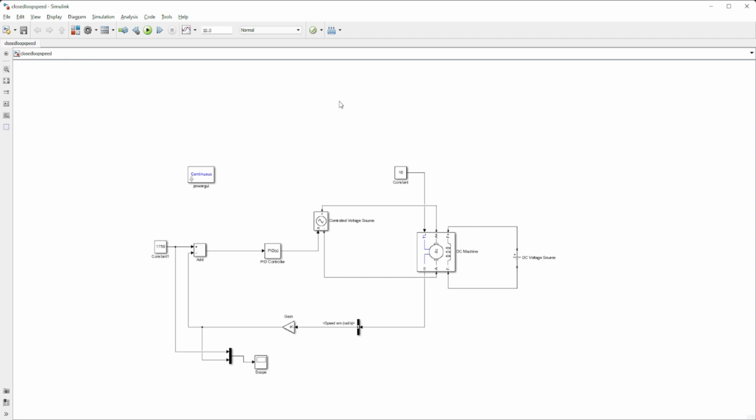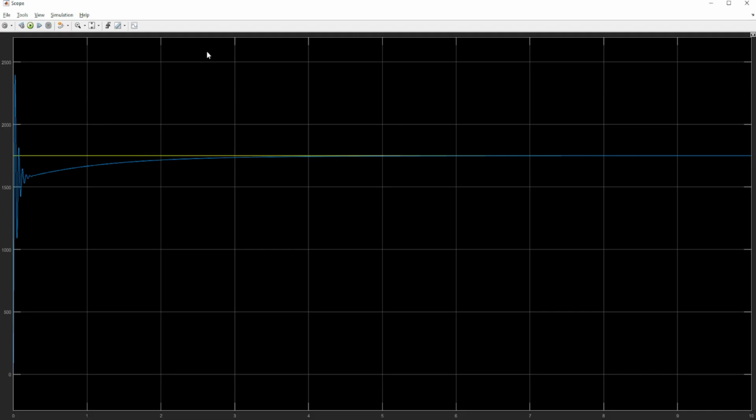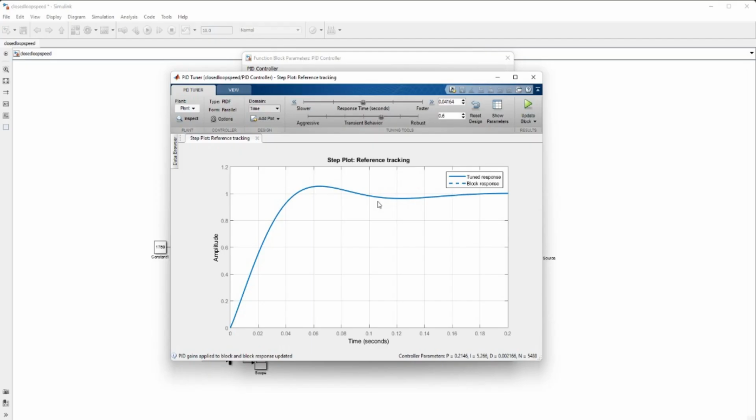And we have used a Power GUI. Now the output of this particular simulation you can see right over here. But as you can see, there is a very big steady state error. So to decrease it, we tuned the PID controller by changing the values of Kp and Ki in the PID such that the steady state error comes out minimum.